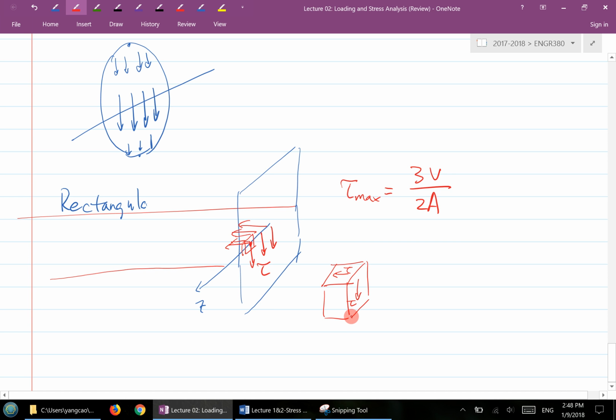If you look at this simple drawing here, it actually tells you a phenomenon. If you go to your basement and you watch the supporting beam, the wood, often in time, what do you see? You probably see a crack along the wood, in the horizontal direction. How the crack is caused is basically because of the shear stress here. And wood is an anisotropic type of material, so you see a horizontal type of crack along the wood beam. So that's your rectangular type of cross section.